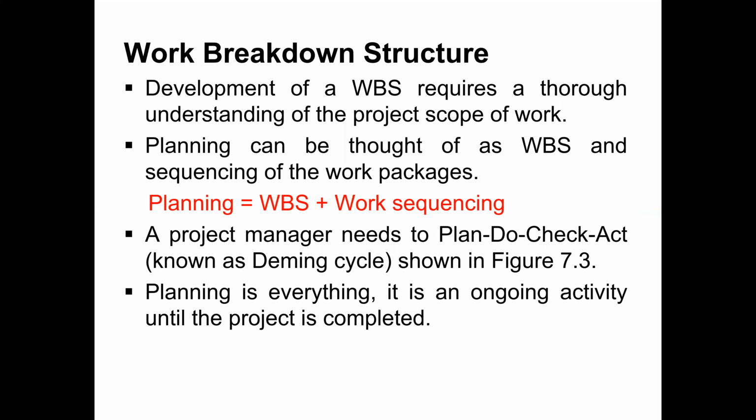Okay, sequence of work. Like first for the bridge, we have to construct the piling, and over the piling we will make a pile cap, and above the pile cap there could be a column. Then above the column it could be a cross head or whatever, the box structure, superstructure. We should know the sequence of work, what should be done first, and then what comes next, and what comes next, and so on. We have to keep the sequence of work for building the project.